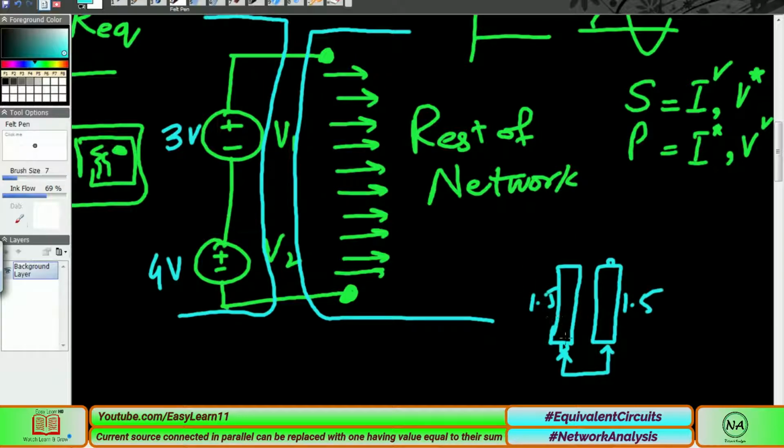After combination, first it is the negative terminal, then the positive terminal. So 1.5 volts coming here, and after passing to this side, this 1.5 is further added to this 1.5 in series to make it 3 volts at the end terminal. After passing this cell, 1.5 volt push is added.